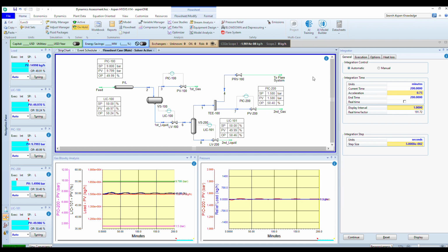The same analysis will be done using dynamic simulation. Dynamic simulation, as per API 521 section 4.3.3, can be used in pressure relief system design and assessment to calculate transient pressure increases in the system. And the key objective from calculating the pressure increase dynamically is to calculate the required relief rate from individual PRDs. The reason for that is conventional methods for calculating relief load are generally over-conservative and can lead to an overly sized relief